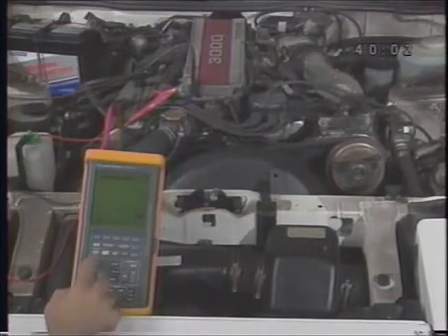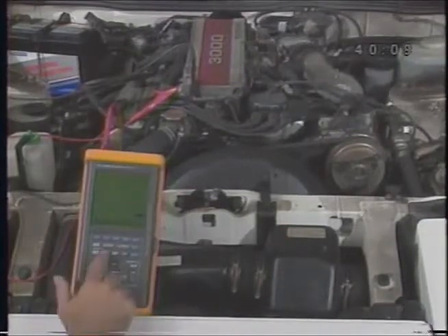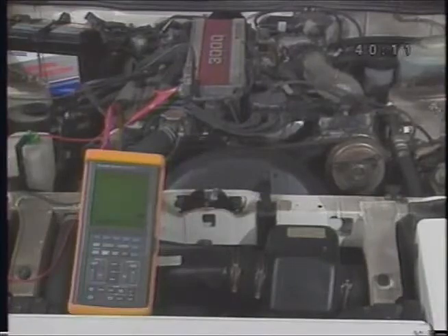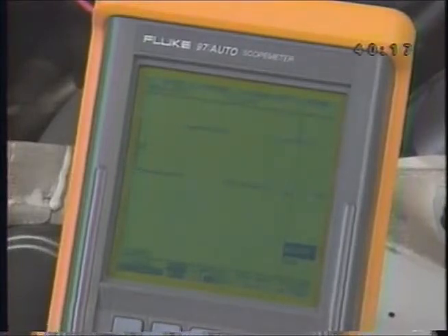Make sure you're set to DC coupling. Start the engine and press Auto Set. Since the signal varies frequency based on engine RPM, the signal should open up as the engine warms and idle speed drops. If necessary, you can readjust the time base or press Auto Set again.